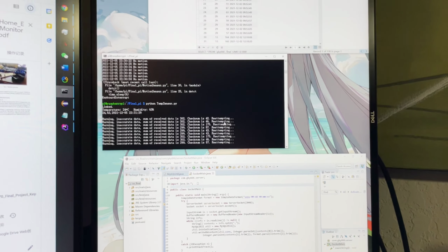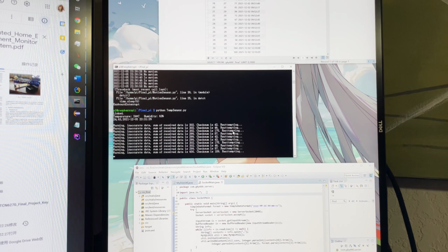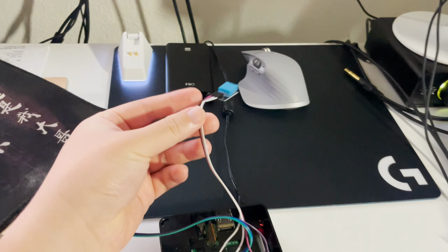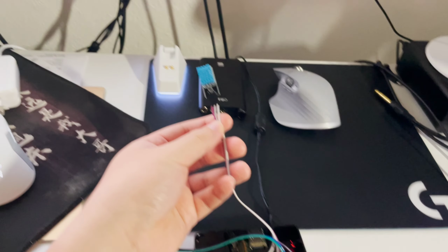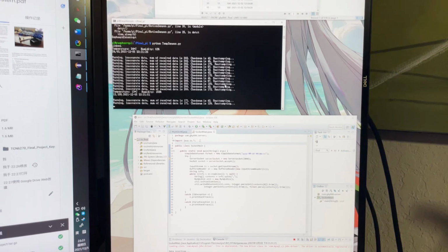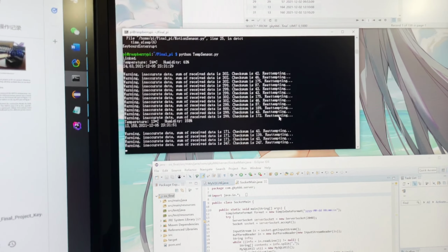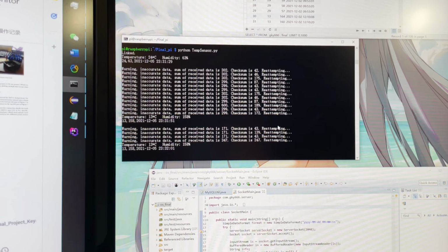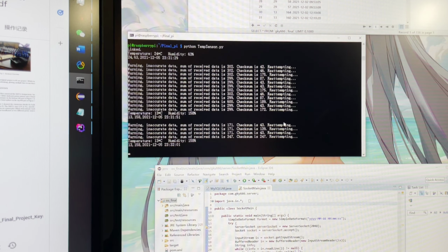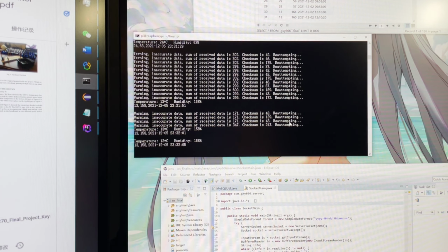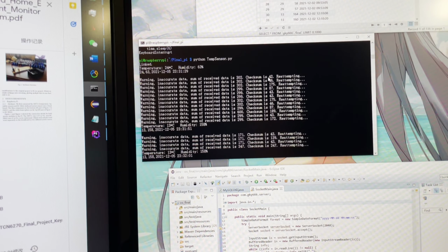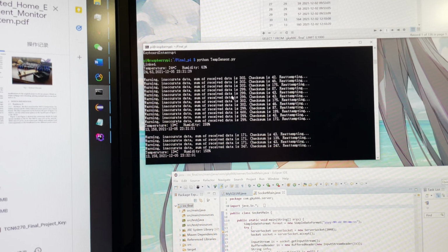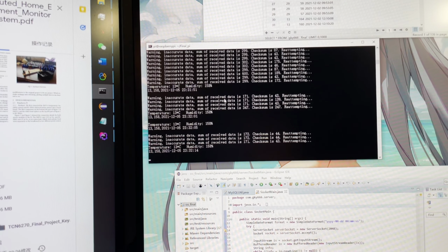As we already introduced in the presentation, because of the wires and the improperly grounded Raspberry Pi, we will have some very wrong readings, like this kind of inaccurate data. Also, a temperature of 13 degrees and humidity of 158%, these are all wrong. But we also have correct data here, 24 degrees and humidity 63%.